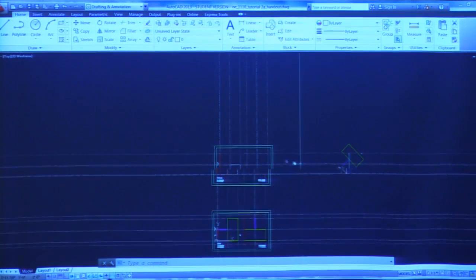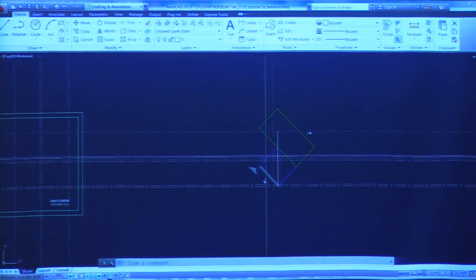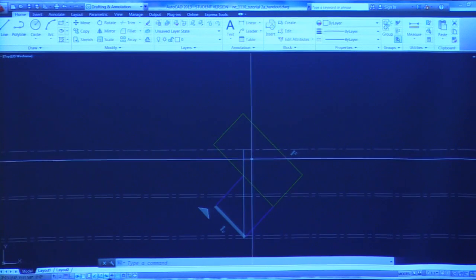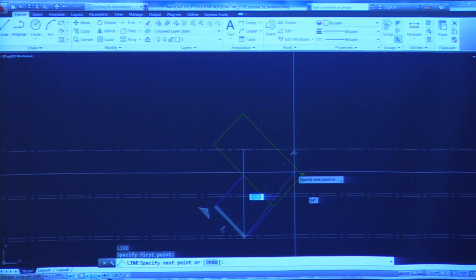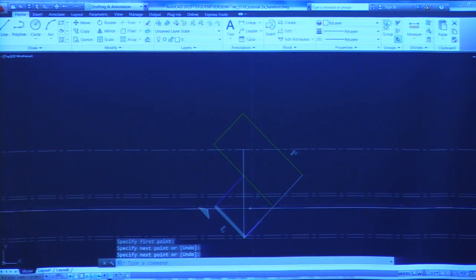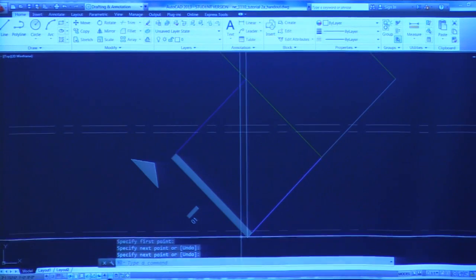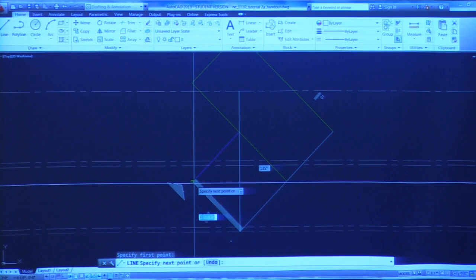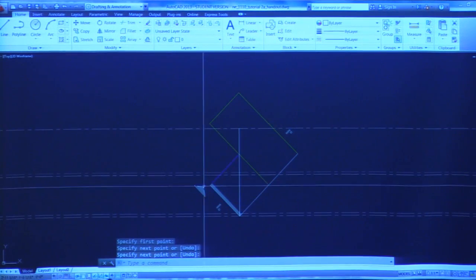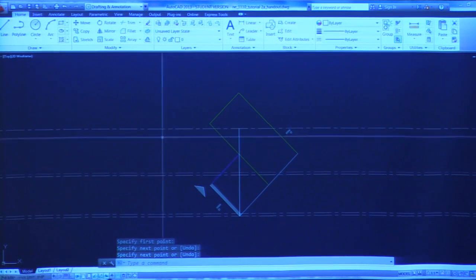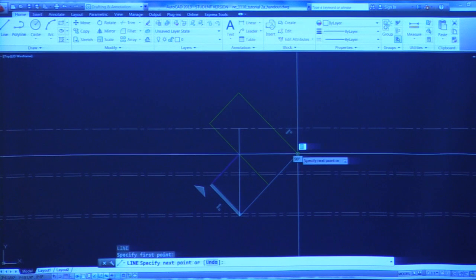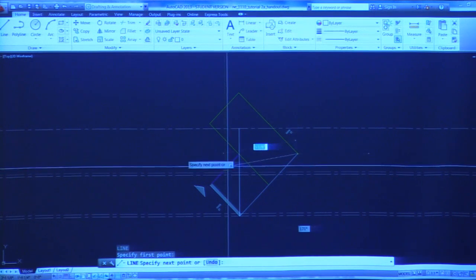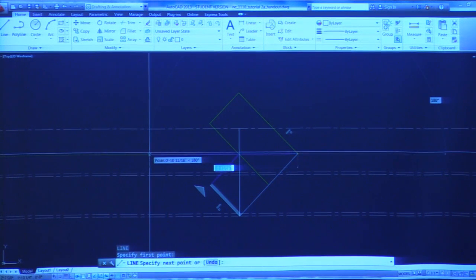So I go back to my file here. Now I'm just going to start by drawing the body of the overall 6 by 6 inch cube. I'm going to draw my x-axis. I already drew my z-axis. I'm going to draw my y-axis. Now here's a cool command. You can see that I can't really draw precisely in the y direction that I want to. So I'm going to type line, L, and pick that point. I'm going to drag across here.